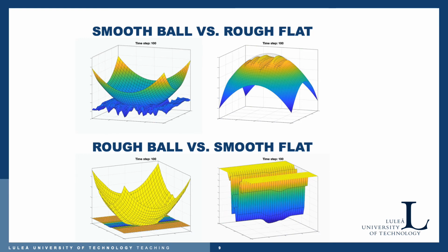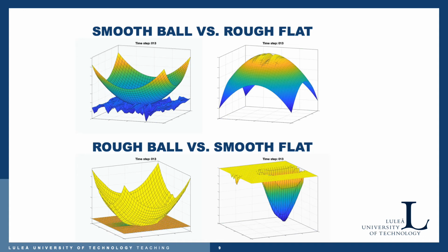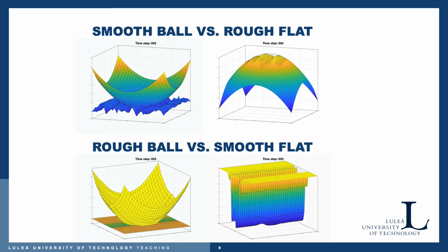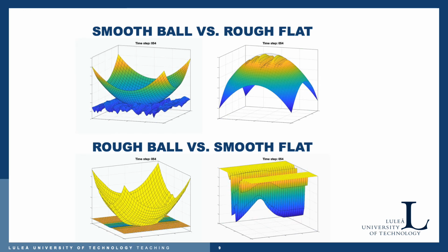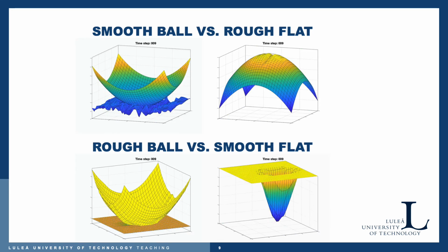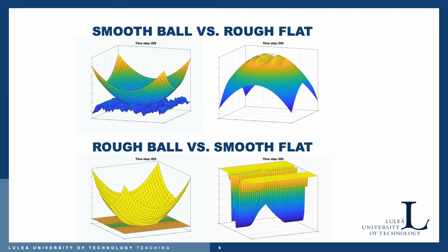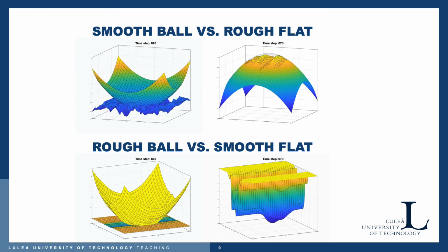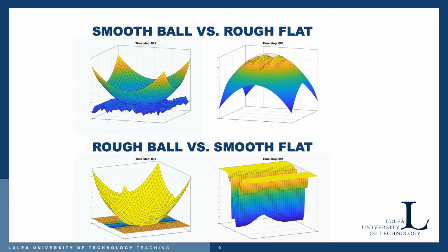Now it starts again, so we move it over the border, it comes in from the other side, and we continue to do that a few revolutions, and therefore we finally obtain a quite uniform wear track, as we can see here.